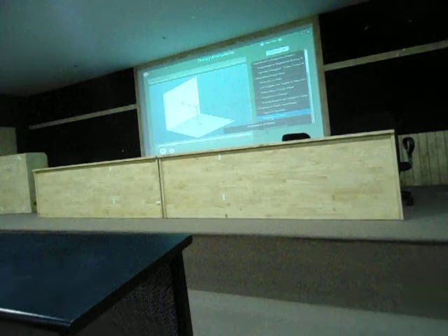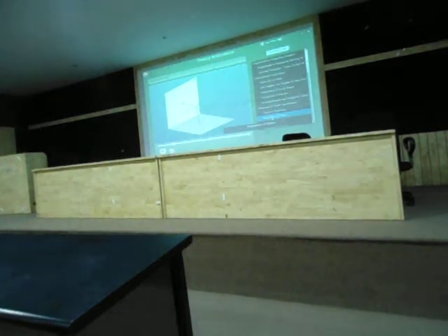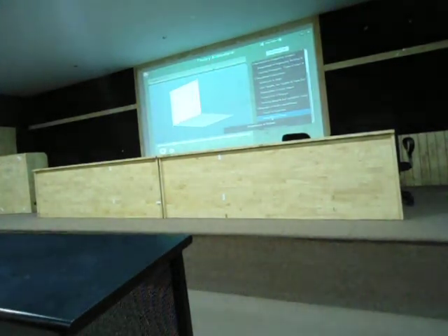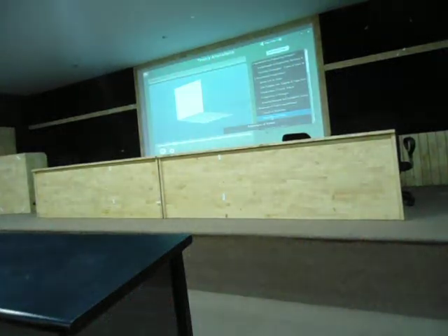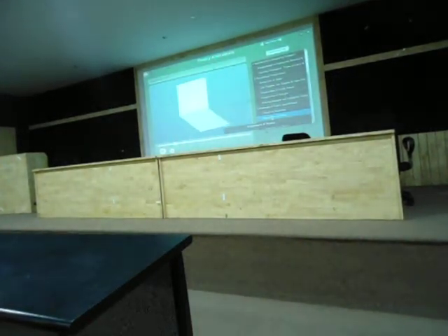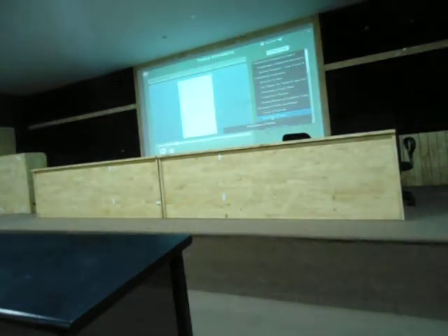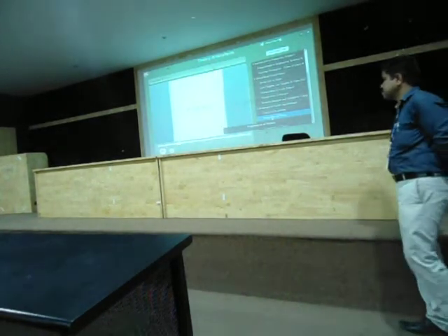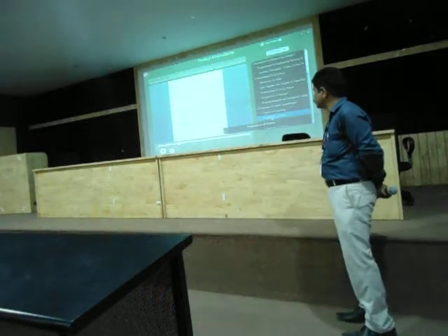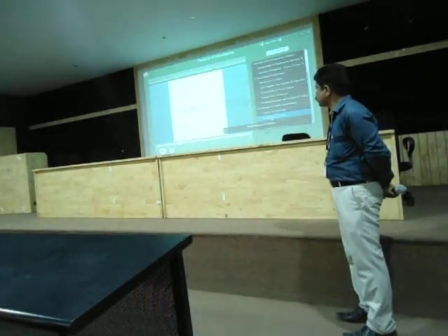So, let's draw this projection onto paper, considering the HP is rotated in the clockwise direction by 90 degrees so that it becomes coplanar with the VP. For this, draw a horizontal reference line XY. Mark the point C anywhere on line XY.